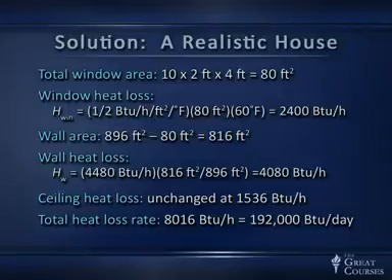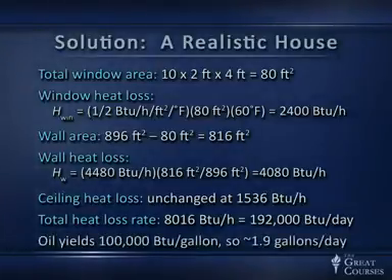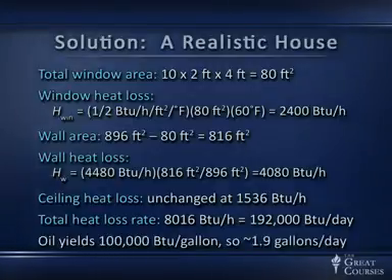The ceiling heat loss is unchanged. Add them all up, you get 192,000 BTUs per day. That takes the oil consumption up from 1.5 gallons to 1.9 gallons per day. So that's a more realistic look at this house.